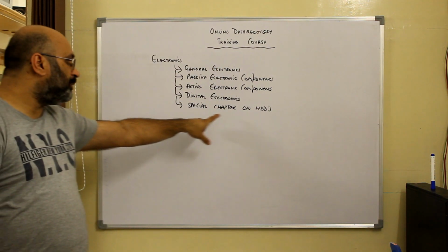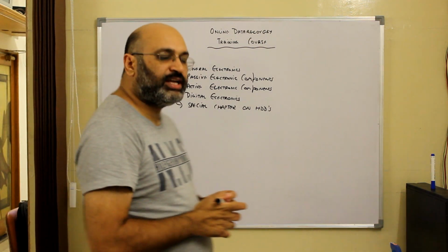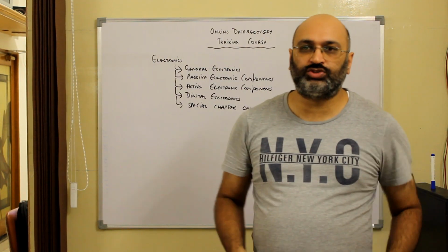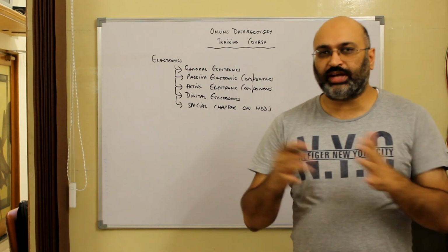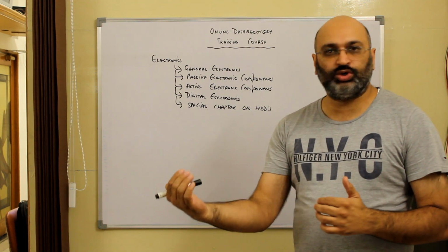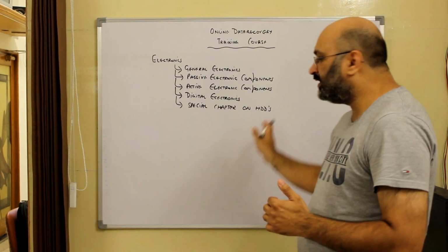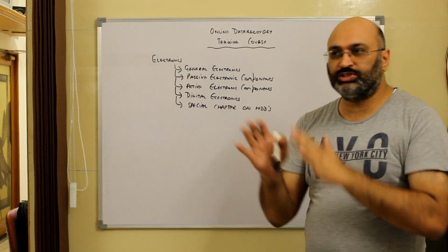So we have a special chapter on hard drives. In this we will discuss different types of connectors, the pinouts of the hard drive, the power input stage, what protections are used over there, for example TVS diodes, 0 ohm resistors, and then how to swap the ROM, all those details.